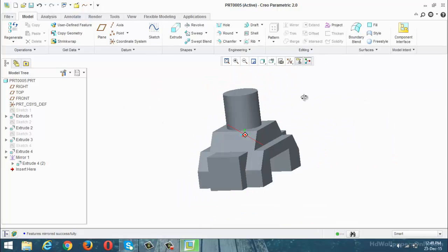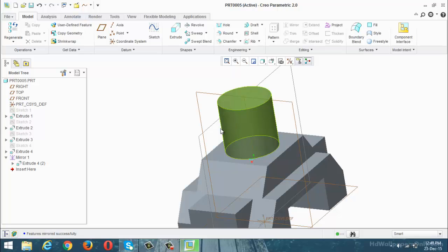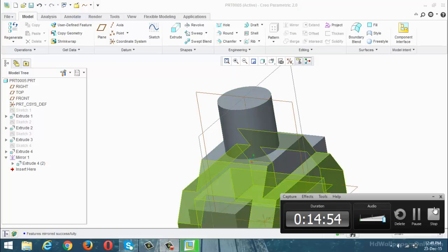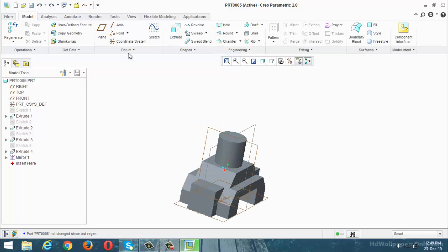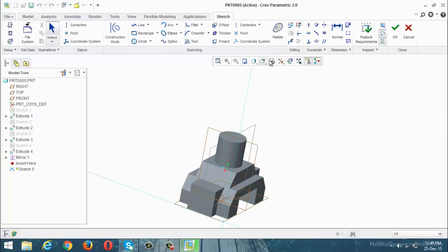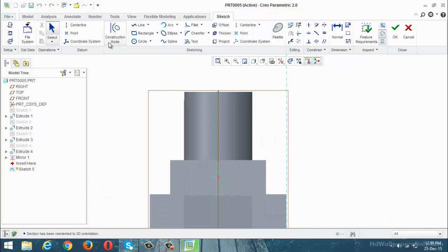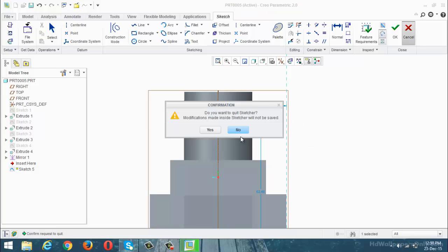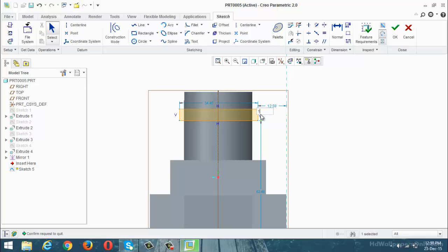Now again I am going to create the holes here. How to design those holes? Now you can see the first procedure for that one. Sketch, select this one, sketch, set it to sketch view. Now I am going to design one in this format. Again how much? Now this one is enough. Any length. Now what is the height? 10. Change it to 10. And positioning is exactly the center location. That means now select the normal option with respect to this one, the 10 value. 10. Okay, just okay.